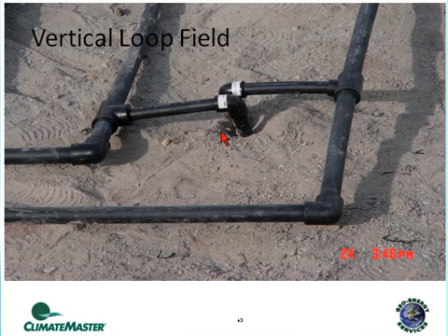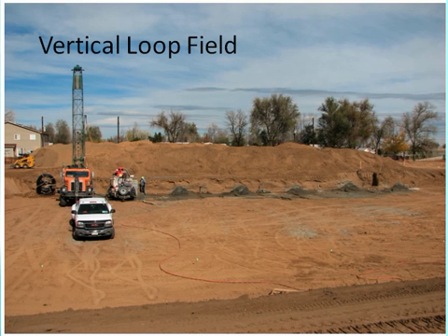Again, our standard practice in our office is our details and our specs require that they do the 90-degree fittings. To me, it looks a little cleaner and is a lot easier to see that it's done correctly. To rely on them to make sure they taper back this edge of this lip here and bend the pipe over and not kink it just seems like there's a little bit more level of risk there, but certainly is acceptable. Here's another installation here where they over-excavated the site.